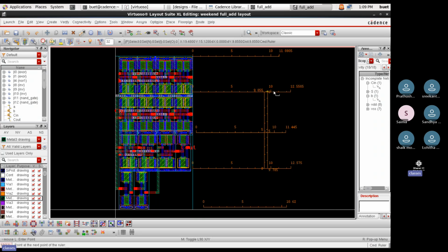Okay, I'm just making it like this. Okay, and to connect all these VDDs, we need a track like this. I'm symbolizing VDD as 3 lines and VSS as 2 lines. Okay, so all the VDDs will get connected.